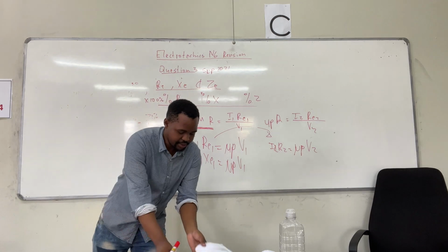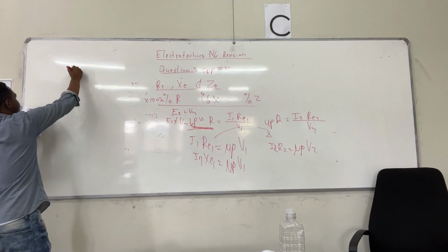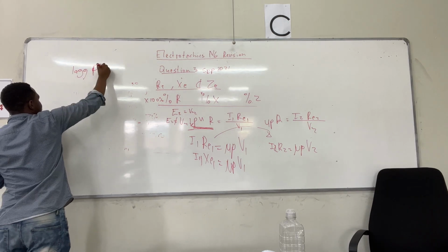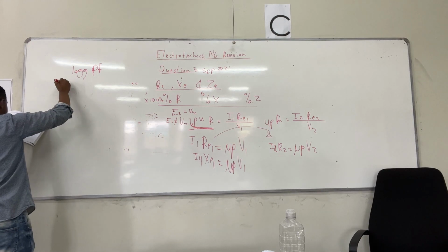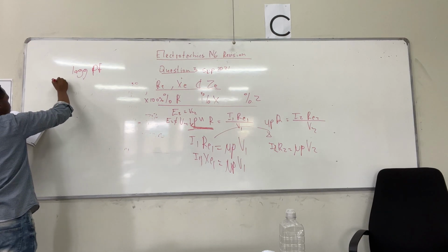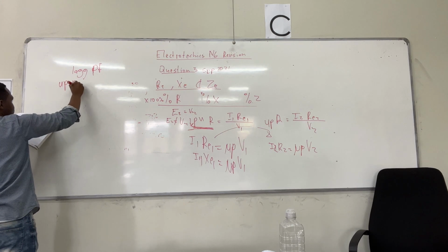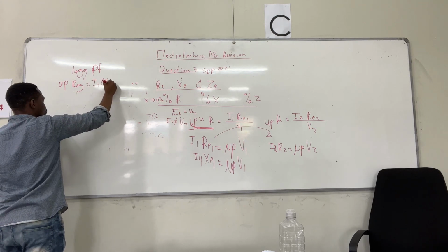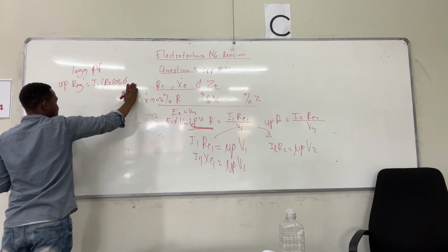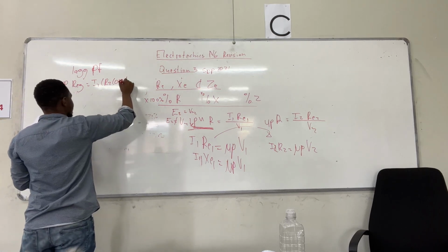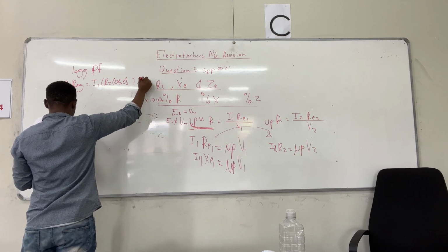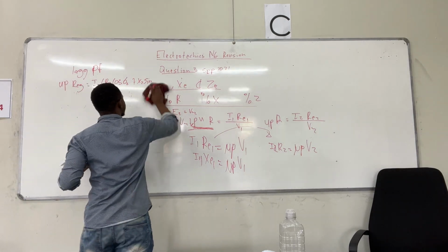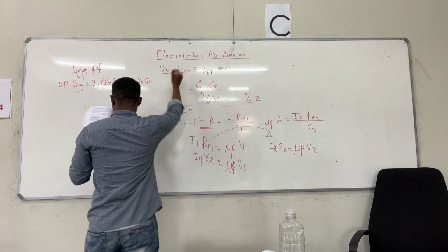The formula that we're going to use for a lagging power factor: the per unit voltage regulation would be I2 R2 times the power factor in the secondary, plus X2 times sine.